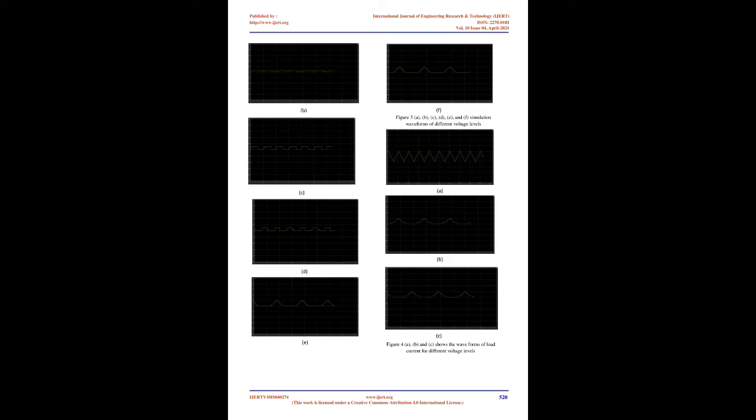Variable or adjustable speed drives generate pulse-width modulated waveforms with rise times below 100 ns. These very rapid transitions can cause large turn-to-turn voltages in inductive devices such as random wound motors, resulting in partial discharge and premature failure. One way to mitigate this problem is to absorb high-frequency energy in the cable between the drive electronics and the motor. This contribution analyses design considerations for optimization of such a cable.